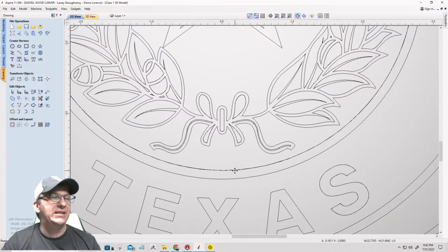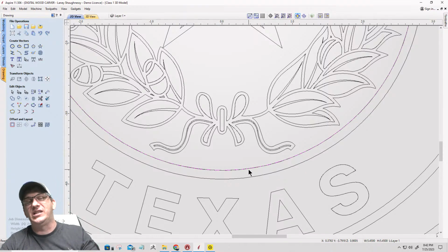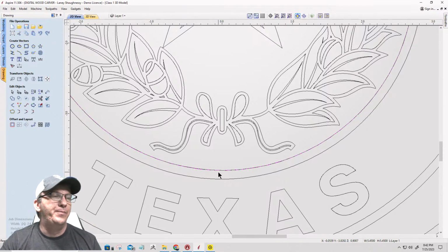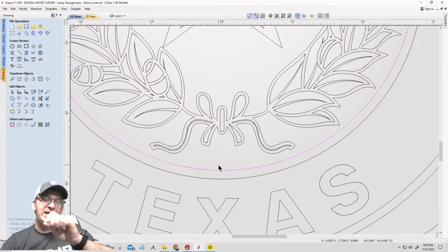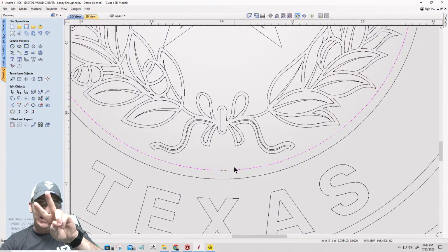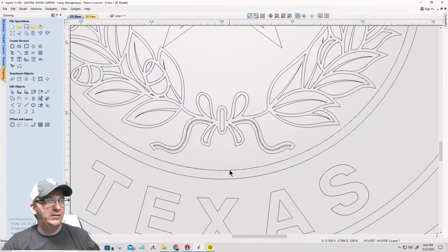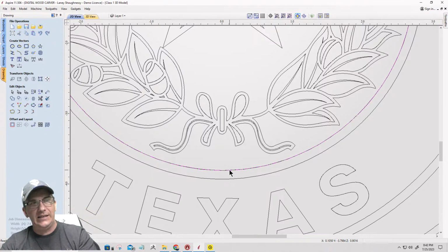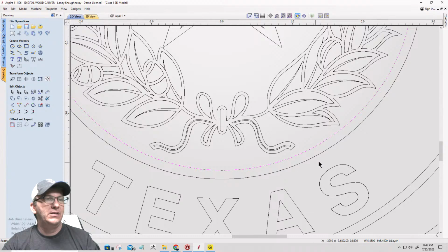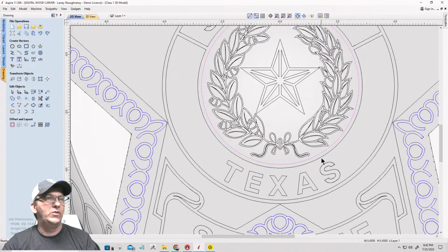So when I select this object here, let me click on it. When I select this object, I actually just selected the top one. And if I select both of them, kind of that right mouse click, drag the box from right to left so they're both selected, and I hold the shift key and I deselect the top one, I can just hit delete to get rid of the one underneath it so that my top one remains.